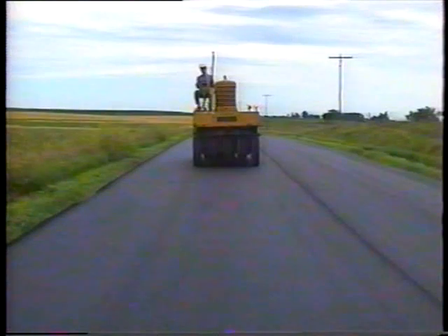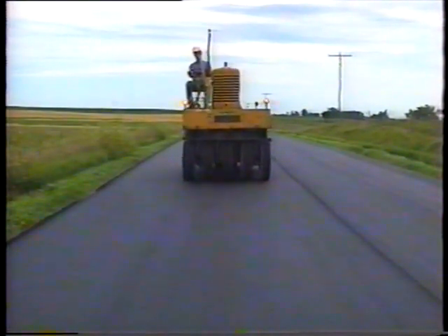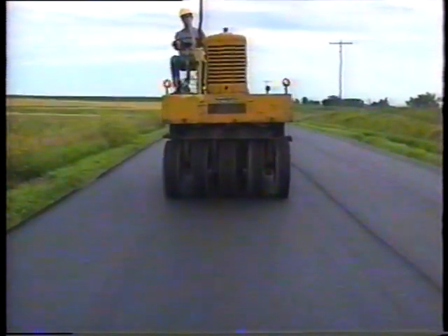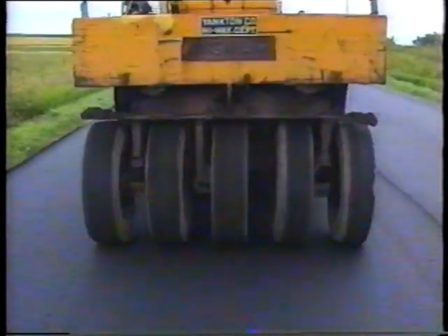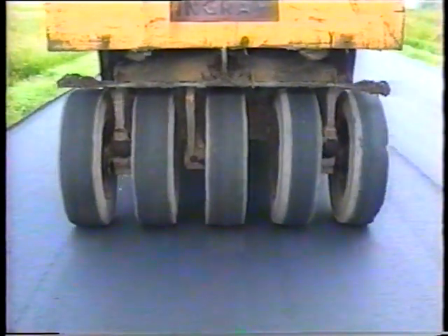Rolling while the mat is still tender will cause pushing or shoving anywhere in the mat, not just the edges. The same problem can also be caused by sudden roller stops and reverses. For steel wheel rollers anyway. For pneumatic-tired rollers, sudden stops and quick gear changes will scuff the mat. And if the mix is cooled too much, almost any change in roller direction may leave marks on the mat.